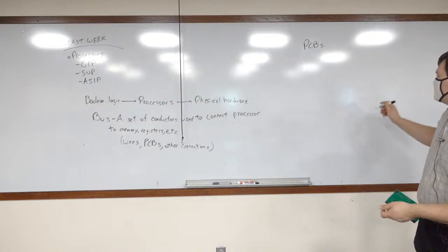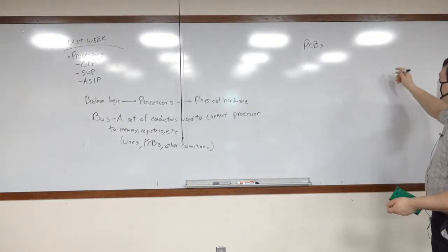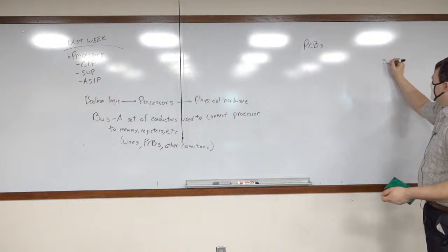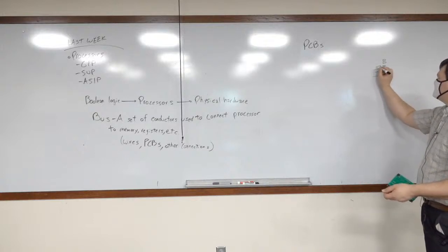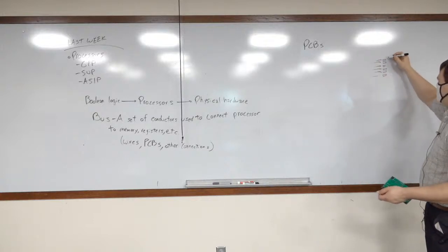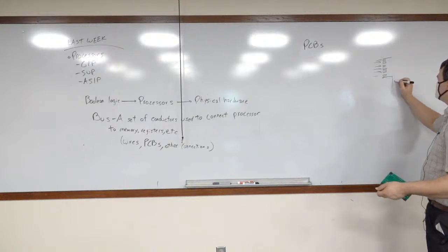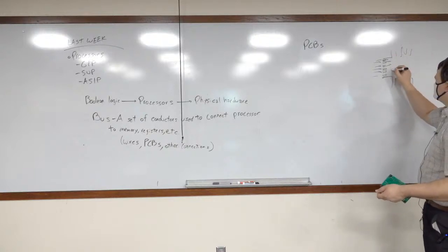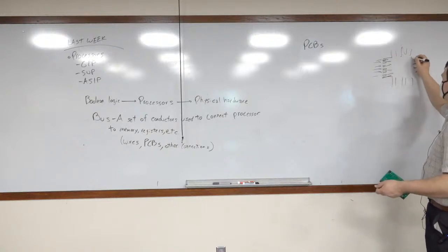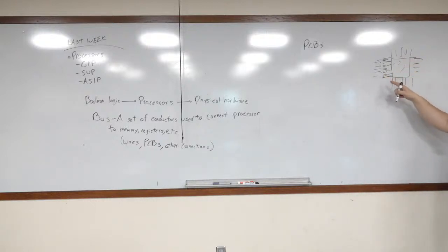They basically put them in the right place, and in the right place there are little pockets of solder that connect to your PCB, and then you just place that chip on, and the chip usually has a number of wires going this way to each one of these, and then it's got the chip in the middle. And then what they do is they just heat this up.